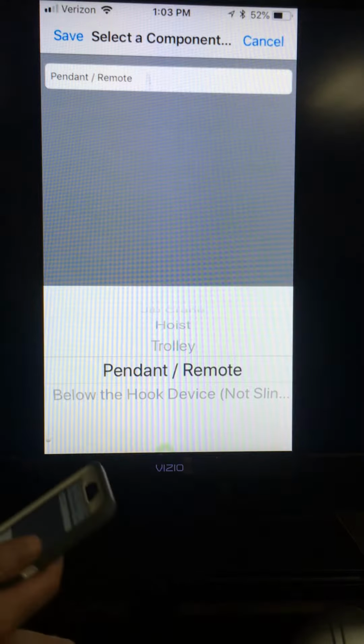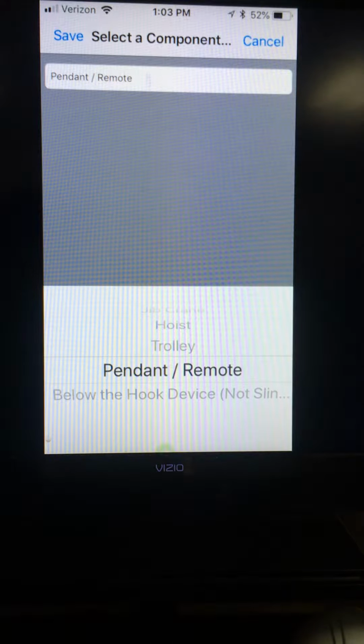And here's the reason why. So if you've got a CM hoist hanging up there and you've got a 2-button pendant station hanging from it, 99% chance that it's going to be the 2-button pendant station that came with that hoist. So the model serial number will tell us how many feet of pendant it had when it was sold. It'll tell us what we need for repair parts.